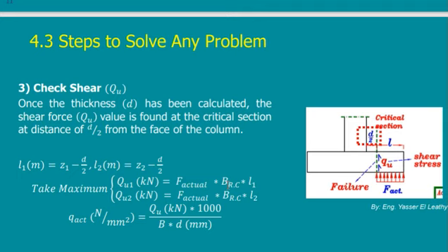So this is punching. They are both types of shear, but the shape of the shear is different. In one, you are shearing part of the section away from the other section, so the bar of chocolate or the foundation has the right to choose the critical section, because it will be broken trying to find the critical section, the weakest section. So this is in case of shear.